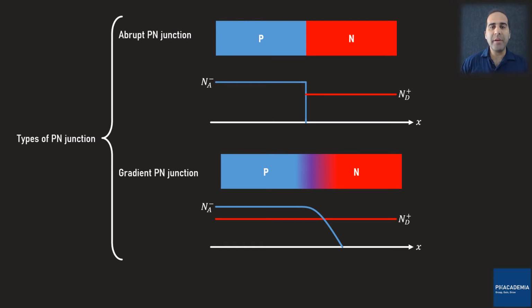What we should pay attention to is that the whole semiconductor is doped by donor dopants with the concentration of Nd. Later in the manufacturing process, the acceptor dopants are diffused from the left side. This is why when we get closer to the junction, the concentration of acceptor dopants Na gradually degrades and finally fades away.